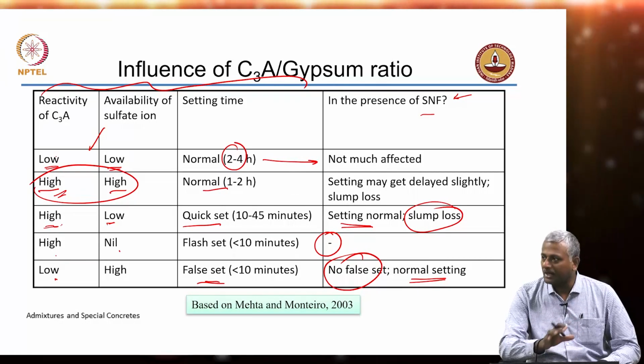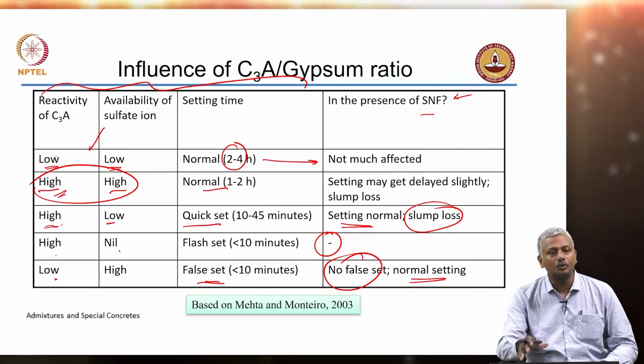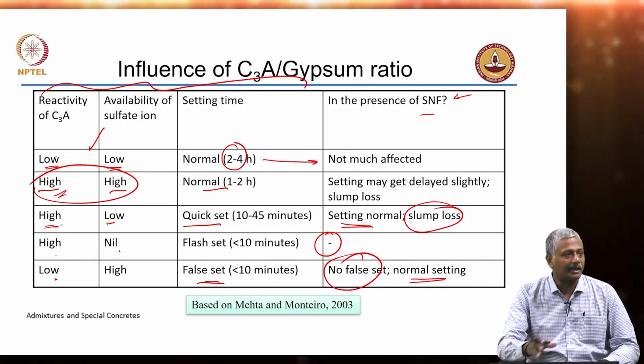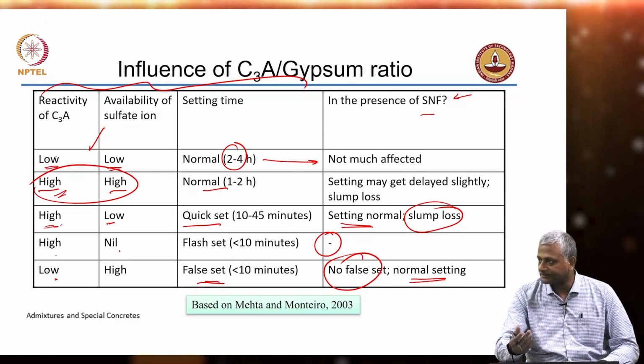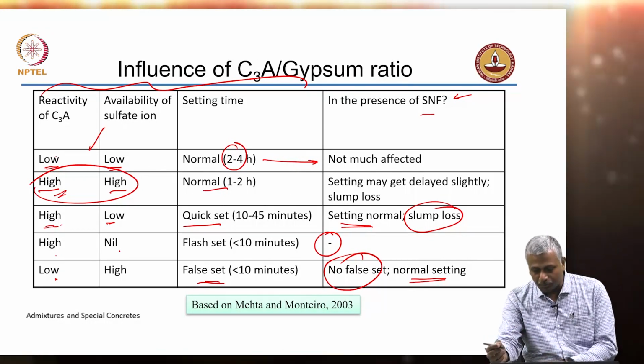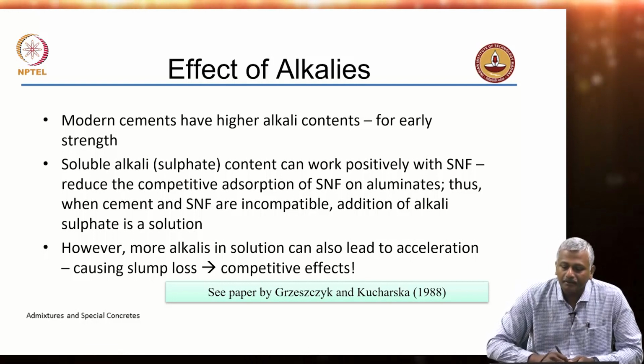So, you have to look at this carefully. That is the reason why we want to do the compatibility tests in the lab before we start adding the admixture on site to do the concreting. Okay. So, it is important to do this to try and understand this.